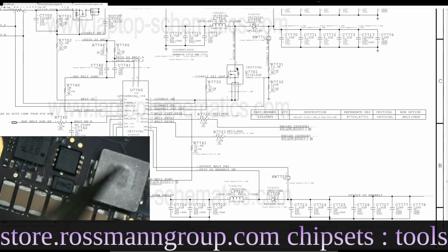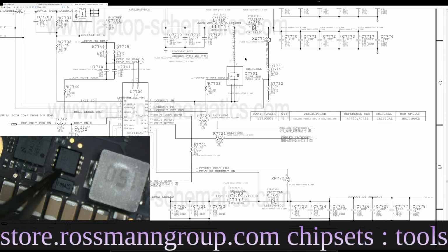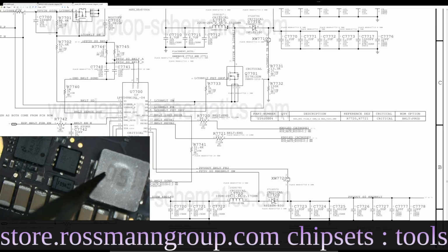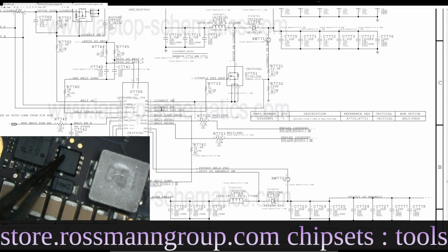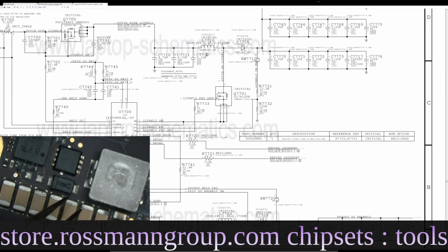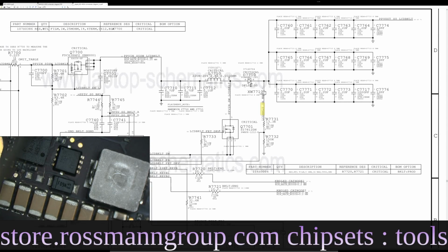This transistor, which I'm going to take a wild guess is this, because it is directly connected to pin 2 of this, which is a coil, is going to short to ground through the LED driver. So the LED driver is going to control this transistor and tell it to short to ground. Now that's going to make the coil rage. At some point, it's going to rage as hard as someone that didn't get their bent nozzles yet, and it is going to send out something along the lines of 30 to 50 volts, depending on the user set brightness.